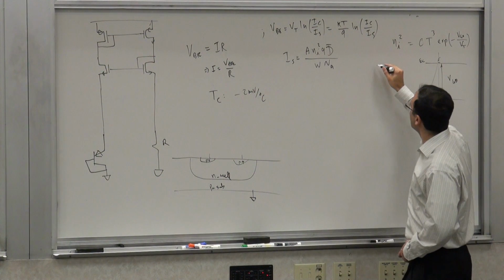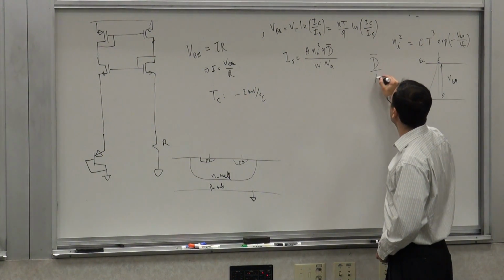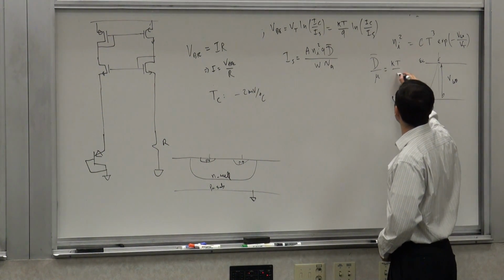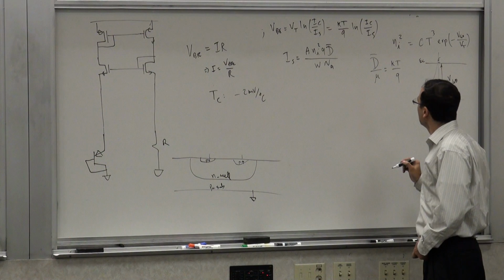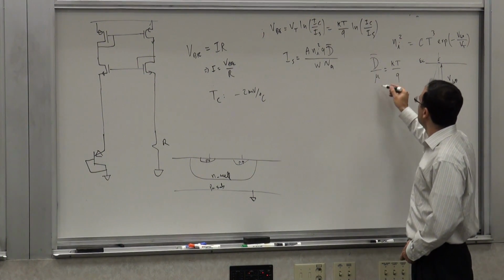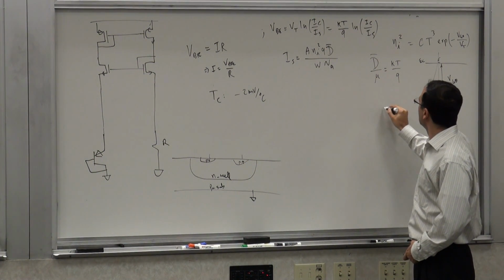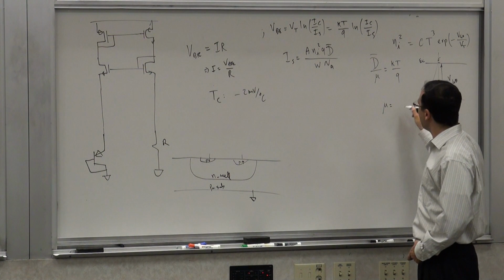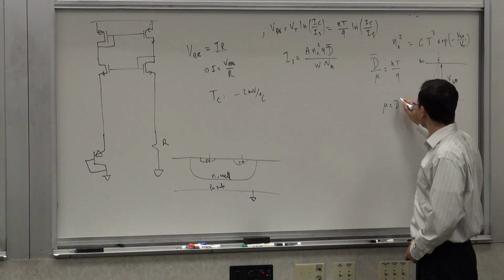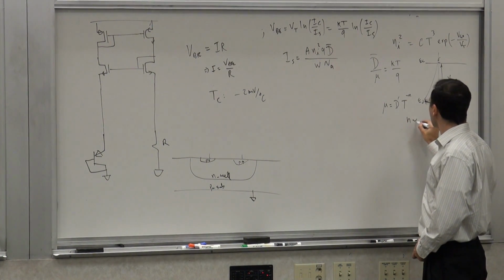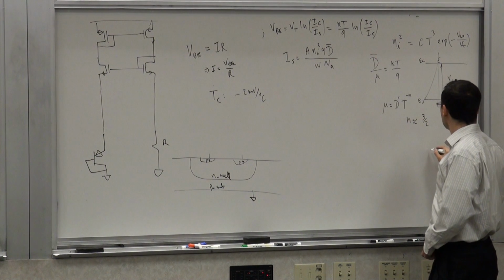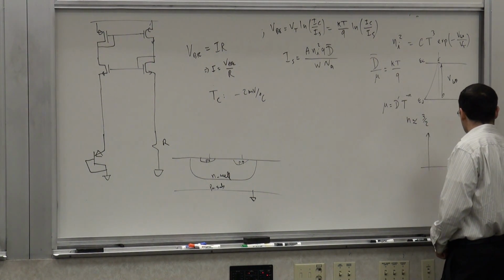So, and then there's the Einstein relation for diffusion. D over mu is kT over Q, and it rhymes. That's the way to remember it. So you can apply this, and basically then you relate this to mu. And mu is basically another constant, D prime, T to the minus n. And at room temperature, n is approximately 3/2. What happens is that mobility changes with temperature like this.